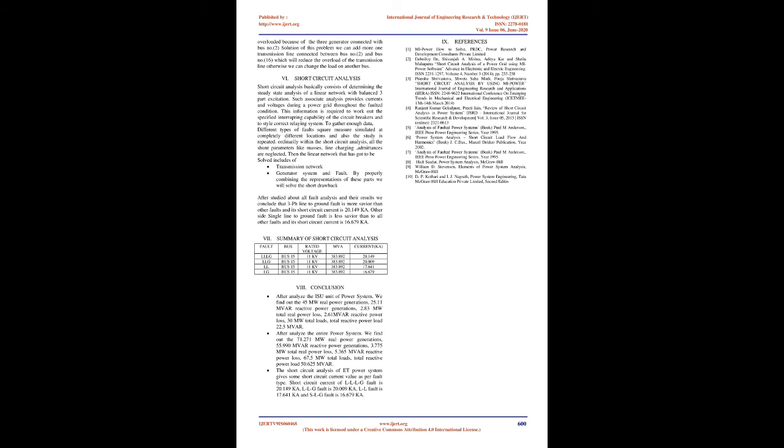6. Short circuit analysis. Short circuit analysis basically consists of determining the steady-state analysis of a linear network with balanced 3-phase excitation. Such an analysis provides currents and voltages in a power grid throughout the faulted condition. This information is required to work out the specified interrupting capability of the circuit breakers and to design a correct relaying system. To gather enough data, different types of faults are simulated at different locations, and the study is repeated.